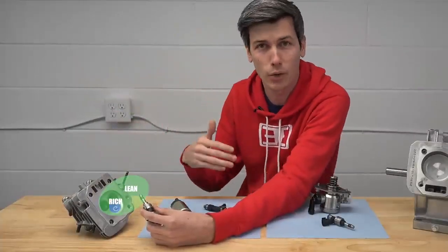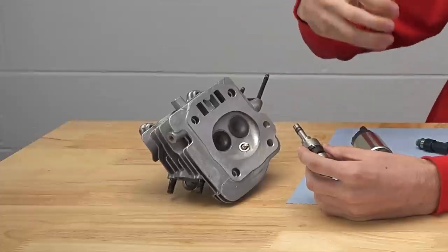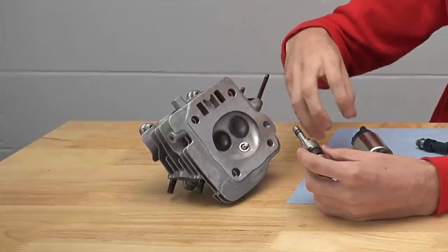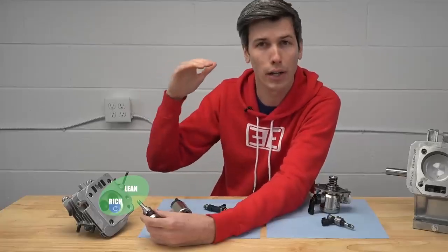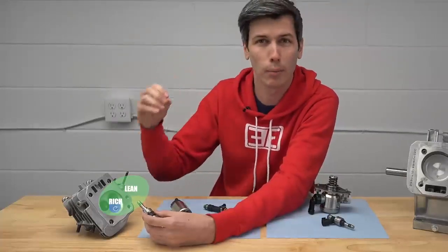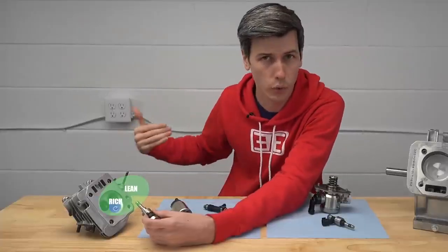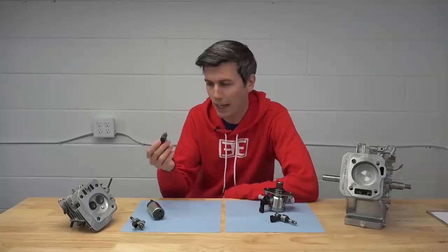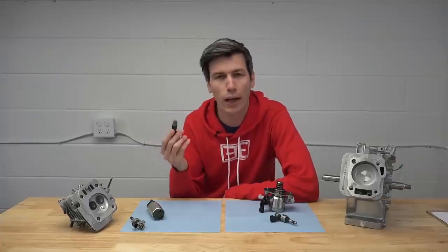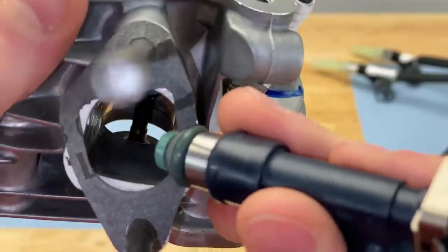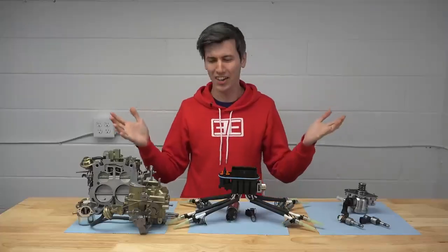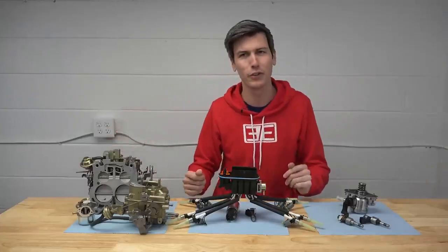Lean combustion alone isn't very stable, but if you can start it off with that rich little pocket, then you can run a higher overall air-fuel ratio, meaning you can operate more efficiently and you can create the same amount of power using less fuel. How neat! Now, of course, by having those port injectors, you now have that tool once again to help keep those intake valves clean. And there you have it, the evolution of fuel injection.